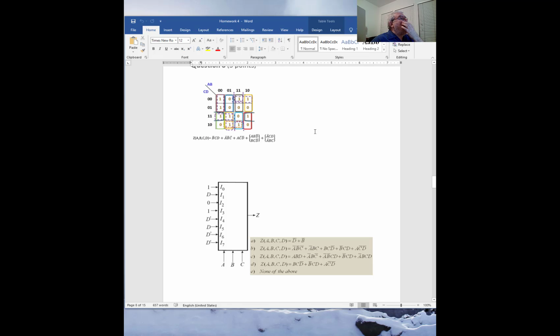So the approach to that is that if you look into the K-map, we don't have any two variable group. So you need to check, because there are many different ways to cover. In fact, if you look carefully at this K-map, we have only one essential prime implicant, which is this one here, composed by B naught, C, and D. This is the one that cannot be substituted for anything else. So you have to be there.